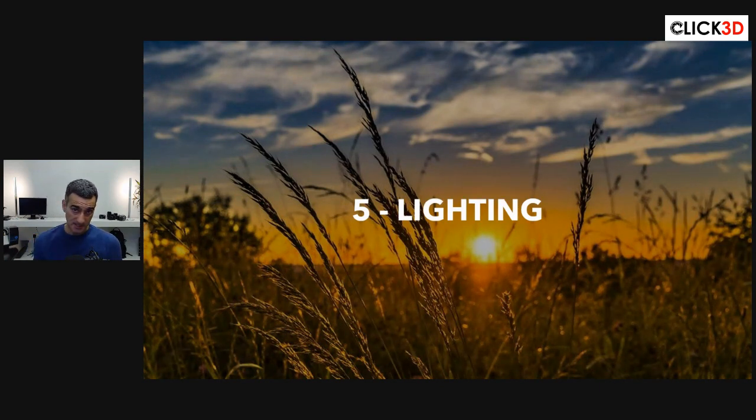Now let's look at the other side here of photogrammetry. Now, what happens with lighting? Well, photogrammetry depends on photographs, which is going to depend on photography best practices. So if you have poor lighting, if it's really, really dark, you need to take measures to either add light, reduce light, make the light more even, or whatever it is that you need to do in order to bring out as much texture as possible of your subject.